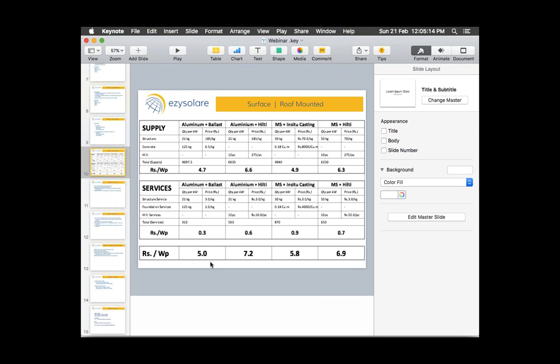However, with SS, we have to understand that at some point we have even seen SS fasteners cracking at site. So we have to be really cautious, because Dacromet is just a coating, right? It's not the material. So we have to be very sure of the material specifications during the connection design in our structures, and what kind of design material we are using. Over that, if you have a Dacromet coating, it would serve the purpose of SS. However, we don't recommend using it for the modules, because module manufacturers explicitly tell us to use SS fasteners for module mounting.